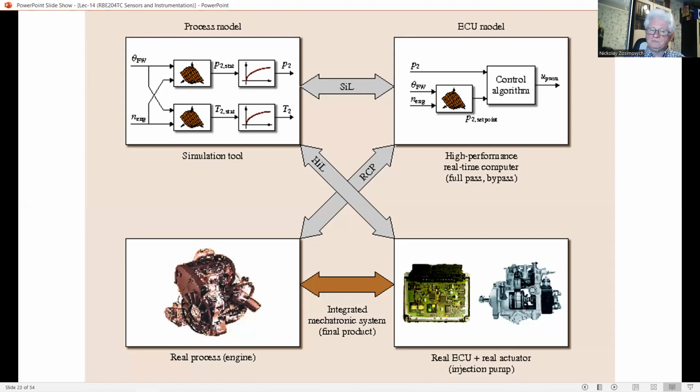Different types of sensing and information acquisition and transfer are involved among all these various types of components. For example, a servo motor, which is a motor with the capability of sensory feedback for accurate generation of complex motions, consists of mechanical, electrical, and electronic components. Its main mechanical components are the rotor, stator, bearings, mechanics of the speed sensor, such as an optical encoder, and motor housing.